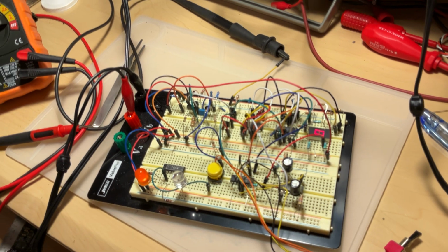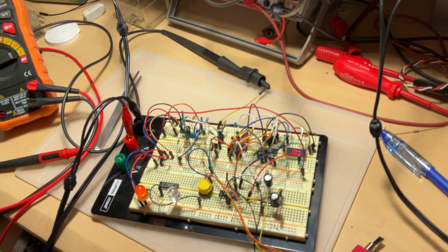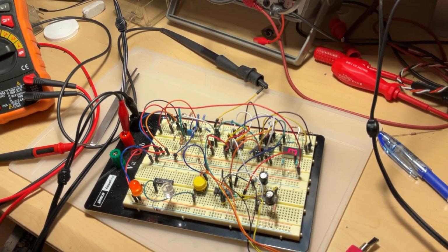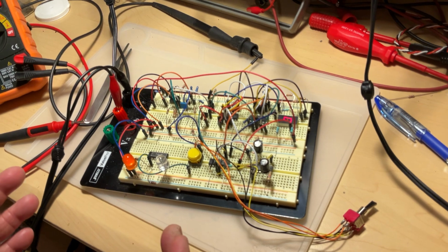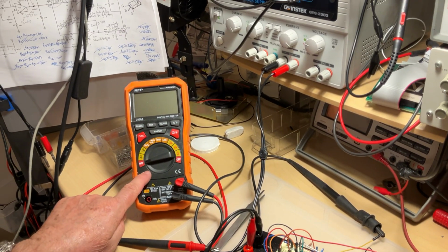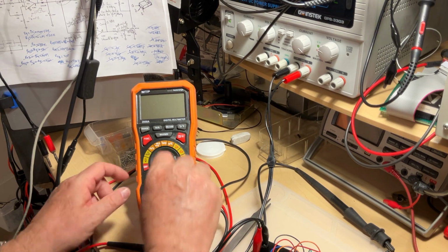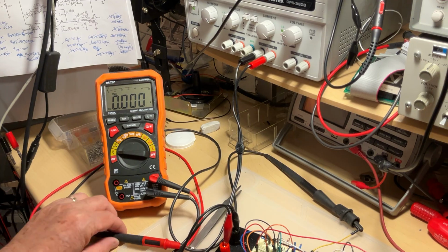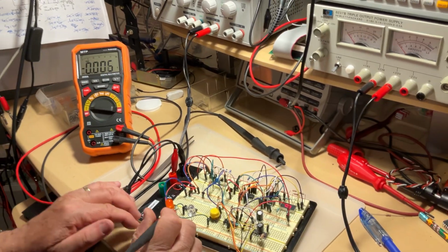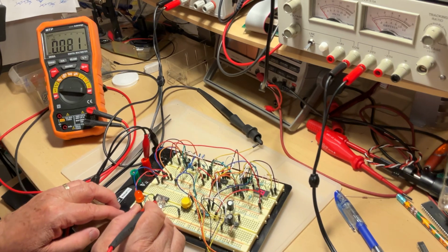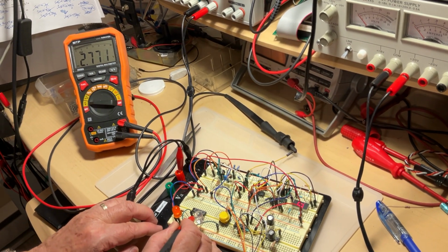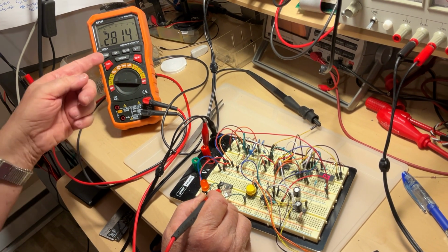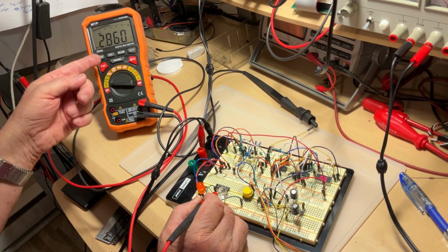Now surely, as you can also recall, I was showing you some pictures on the oscilloscope, but not everybody has access to an oscilloscope. For that reason, what we're going to use to take measurements normally is a standard digital multimeter, and if I put it on the voltage, we should be able to measure some voltage. But take a look what happens. If I measure it here, for instance, this is going to be the input where the LED is connected right now, it is about 2.7, 2.8 volts. It's not 5 volts.